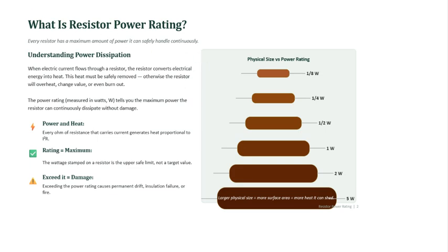So on a resistor, if we say that a resistor's power rating is, for example, 2 watts, this is just an arbitrary example now, what we are saying is that this is the maximum that that particular resistor can take. Anything beyond 2 watts, the resistor will have problems. It does not mean that 2 watts is what the resistor should operate upon, but it should not go beyond 2 watts. Many times it should not even go close to 2 watts.